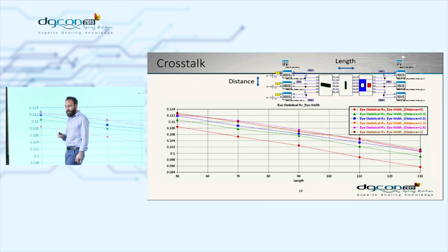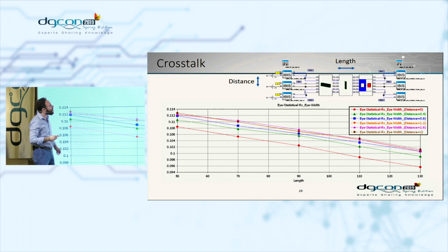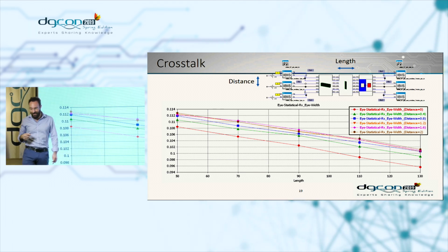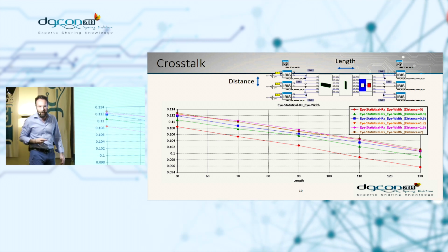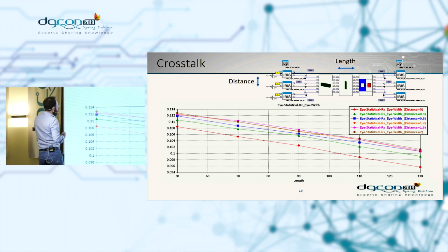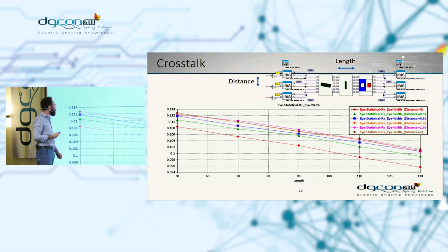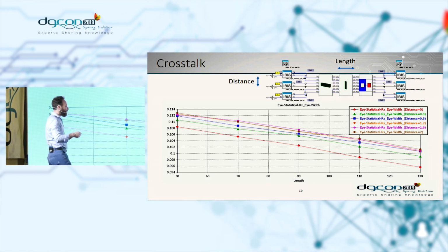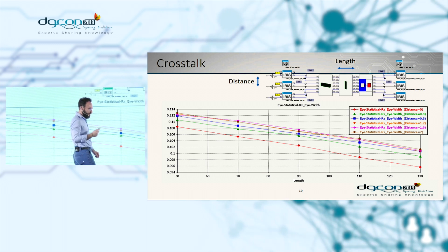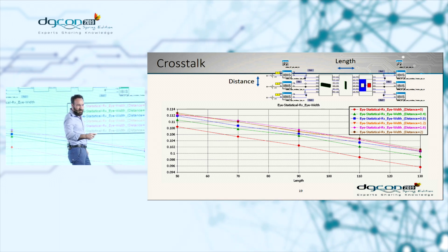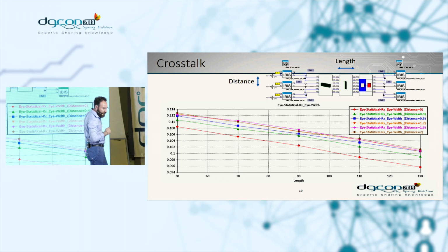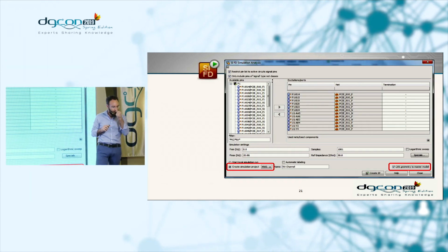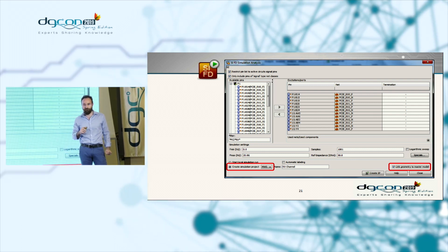Same story when we are trying to enforce or use a very high-speed net, a high-speed digital communication. But basically, the S parameter, the transition, is not so bad. Also, the eye diagram related to this S parameter more or less can be usable for a very high-speed communication. But we forgot something. We forgot the connectors.